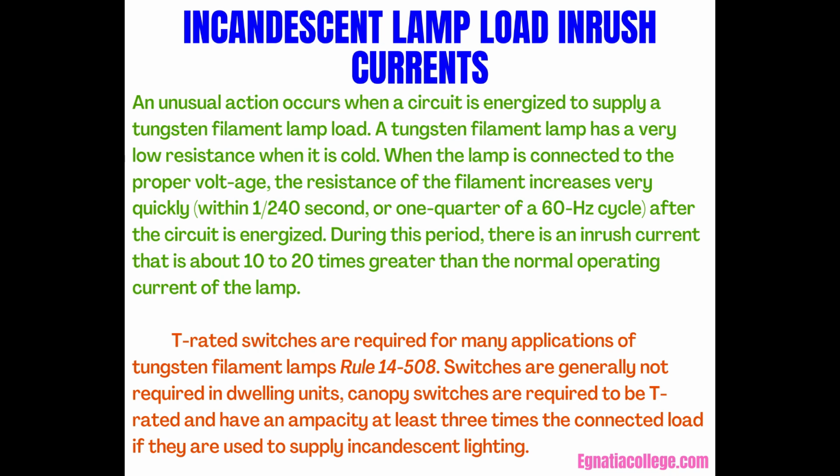Rule 14-508. Switches are generally not required in dwelling units. Canopy switches are required to be T-rated and have an ampacity at least 3 times the connected load if they are used to supply incandescent lighting.